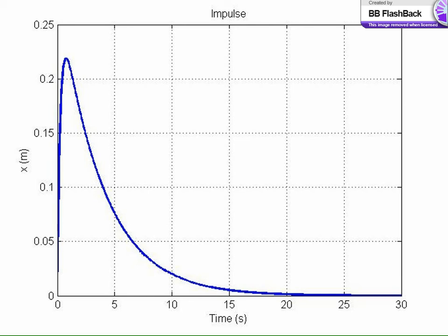So I've got a kind of trick question for you. When we're designing a system, do we want it to be underdamped, critically damped, or overdamped? Critically, you would think that. We actually want it to be underdamped. A lot of the parameters are difficult to estimate, so it's extremely difficult for us to get precisely a critically damped system. With an underdamped system, you have a lot more leeway.